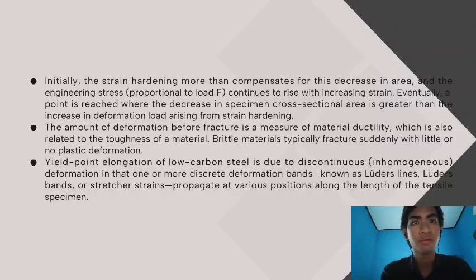A similar behavior occurs with some polymers and superplastic metal alloys, in which a neck forms and grows in a stable manner, with material being fed into the neck region from the thicker adjacent region. This type of deformation in polymers is called drawing.